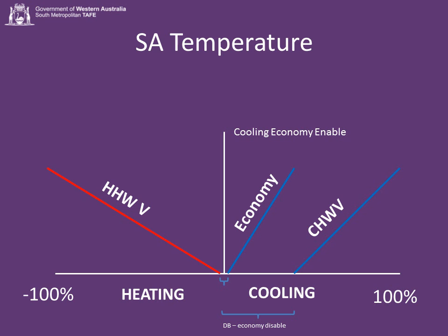This is a slightly more complicated diagram. Now with this diagram, for the initial cooling, I'm using the dampers. I'm mixing in the two different temperature airs. So from say 0 to 30% of economy loading, I will use the dampers. I call that economy because I'm using air. I'm using passive things to cool. I don't have to pay for air, it's just there.